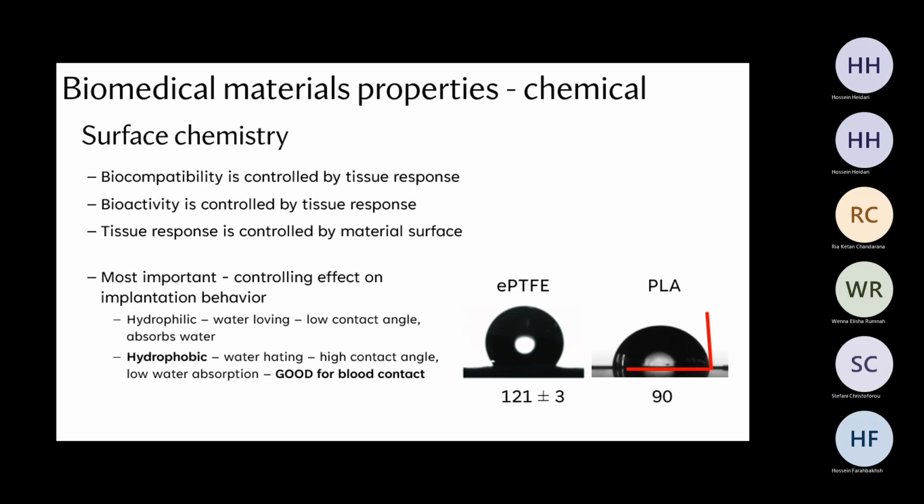Okay? So basically, if we have a low contact angle, we're looking at hydrophilic materials. As this angle here reduces, it means that the droplet has spread. As it increases, it means the droplet is retaining its shape, it's not getting absorbed by the surface. So this is a hydrophobic versus hydrophilic material. Now, we're actually looking for the equivalent to the EPTFE.